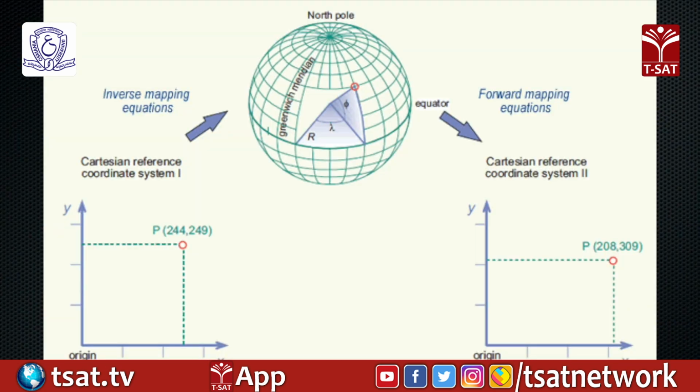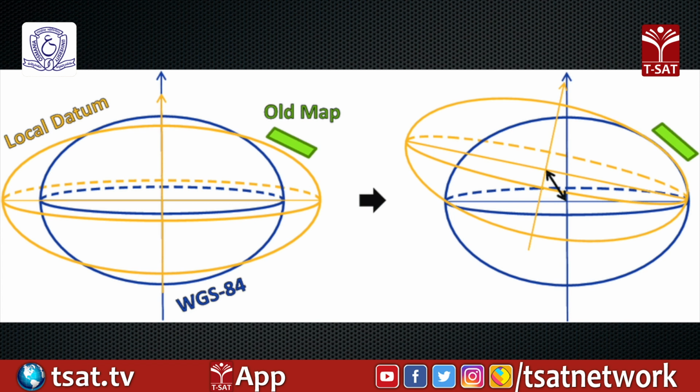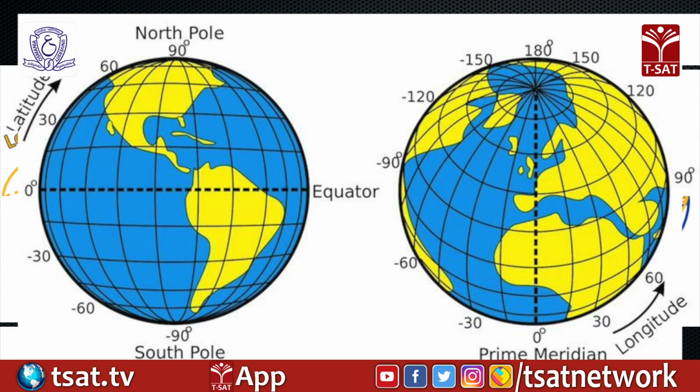In the process of projection, the Earth's surface is transformed to a plane, and the outcome is a map projection ready to use for a projected coordinate system. Projection converts data sets from geographic coordinates to projected coordinates, and reprojection converts from one system of projected coordinates to another system. Typically, projection and reprojection are among the initial tasks performed in a GIS project.